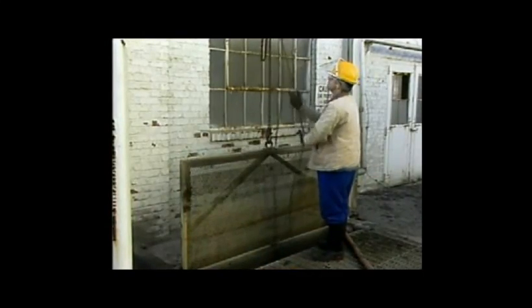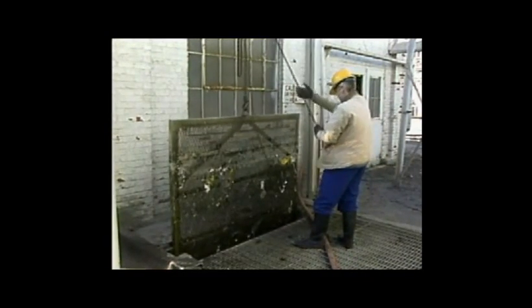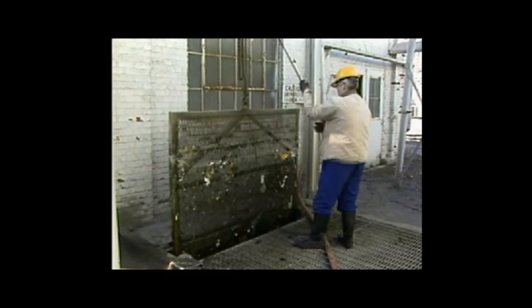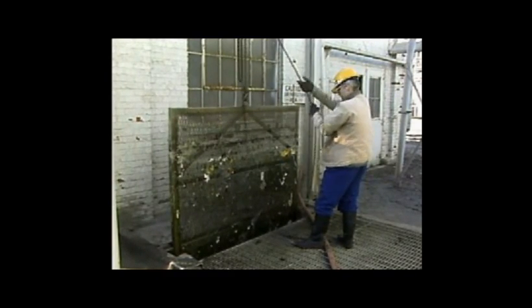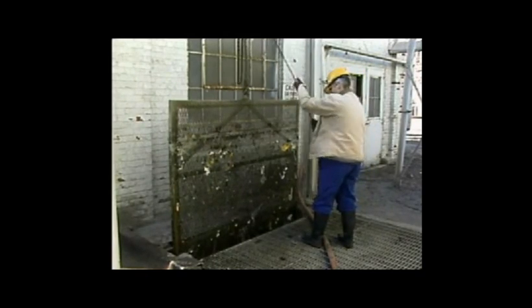Often, screens or filters are placed in front of a pump suction. Screens are used to prevent trash or other foreign material from entering the pump. A plugged screen could restrict water flow into the pump, and cause the pump discharge pressure to drop below normal. To prevent this problem, the screen should be checked and cleaned or replaced periodically.